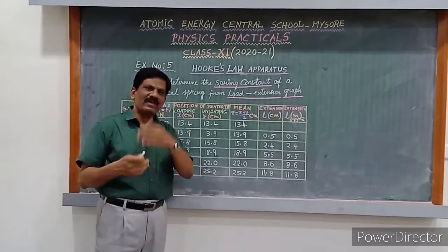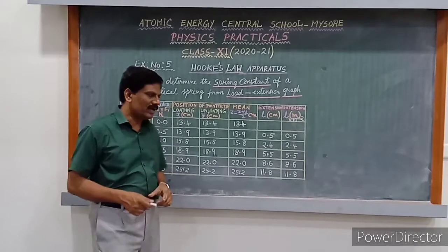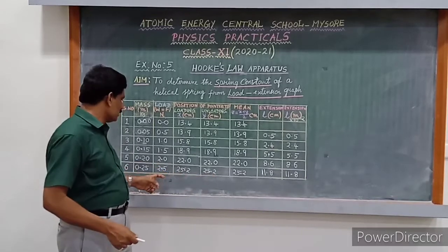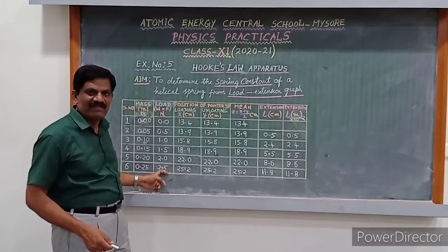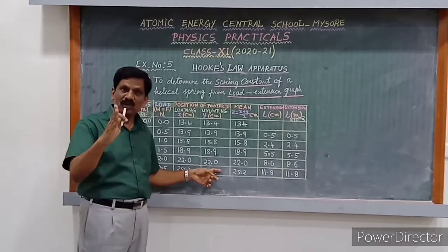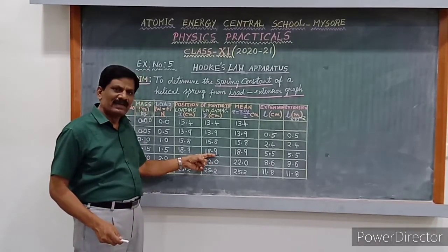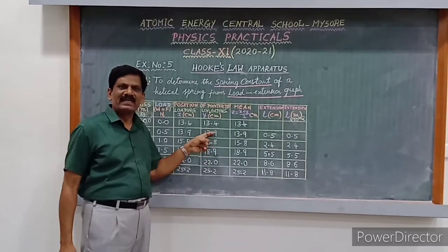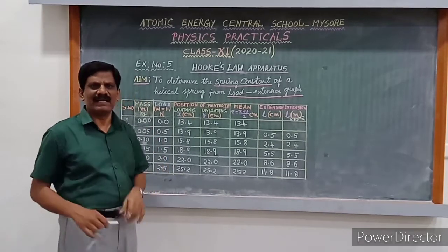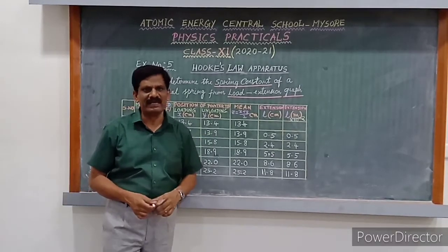Again I told you, we will detach the loads in equal steps of 50. Understand? So I start now with the last reading, namely 25.2, for which the load is 2.5 Newton, that is 250 gram weight. Then every time I removed 50 gram weight, I noted the pointer readings, respectively 22, 18.9, 15.8, 13.9 and 13.4.